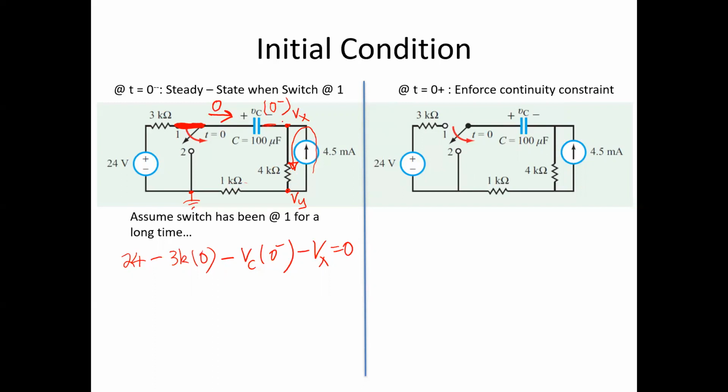Another way of looking at it is just to follow the branch. The branch that the capacitor is on starts at X, but then through this left loop all the way over here, cycles through all these elements and then comes back to Y over here. So this is actually one entire branch. And we know that because of the capacitor, that entire branch current is shut down.